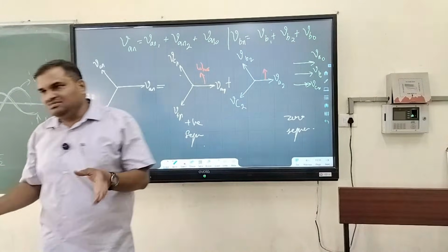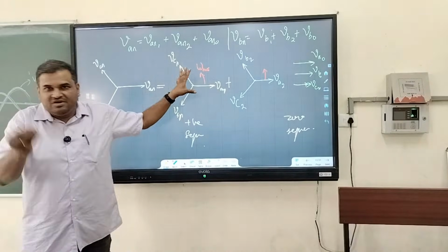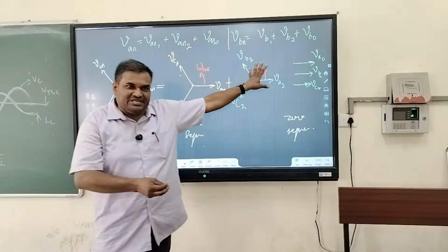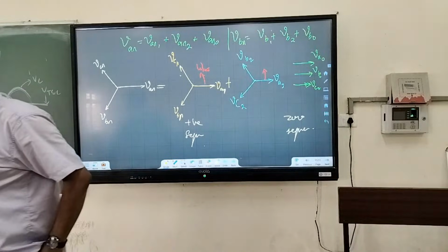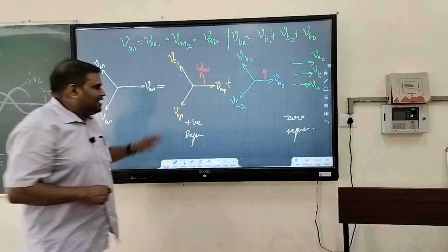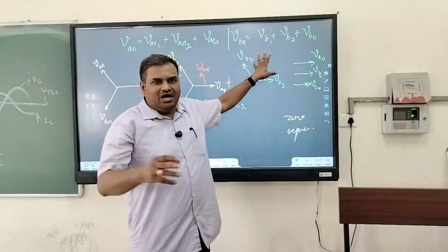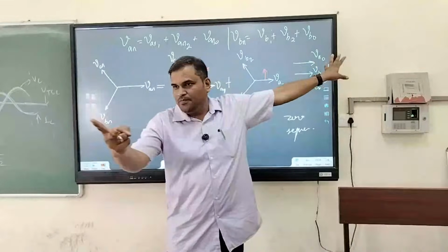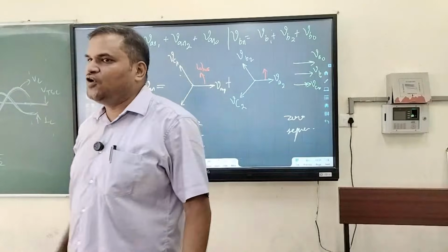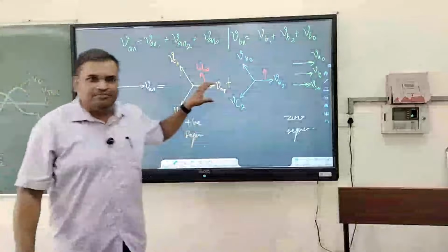If I am somewhere like human, I have got some 50% positive, 50% negative. But there is also a probability that I am unbalanced. In case of unbalance, suppose it has got 90% positive sequence, 8% negative sequence, and zero sequence is 2. Zero sequence is not harmful, but this 8% negative will try to give me a problem.